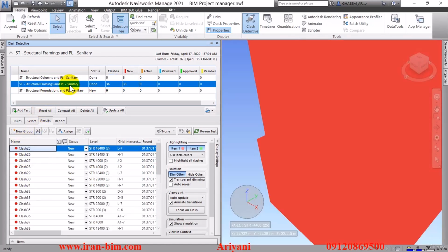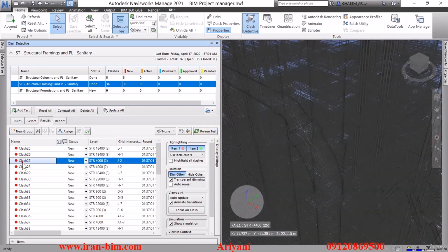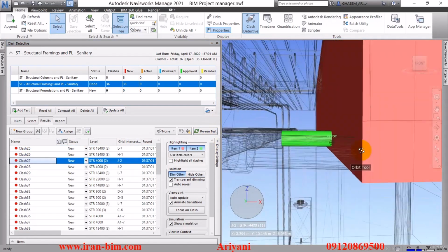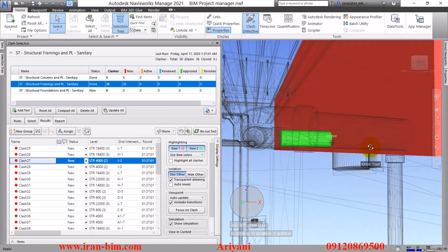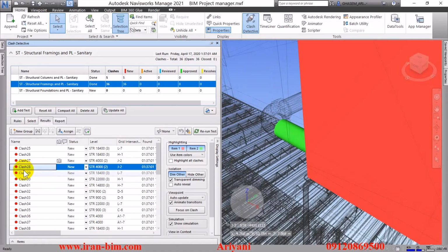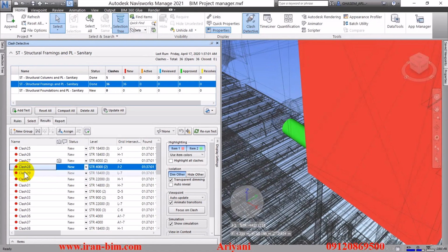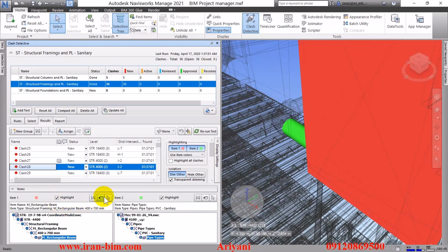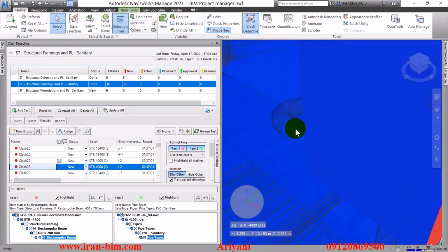Over here, as an example, I'll select the clash 27 that we have down here, and then we'll be redirected to the viewpoint. Alright, so the first way that we can resolve this clash is selecting the clash itself and the item, and then we can see the properties of the item down here. We have an option here that says switch back. Now, what does this refer to?